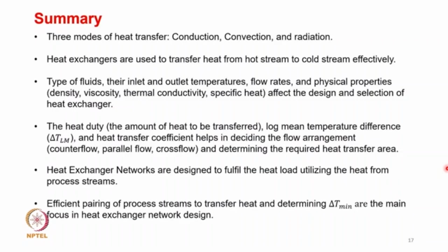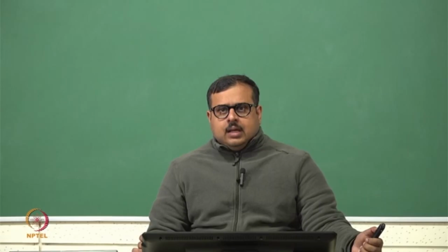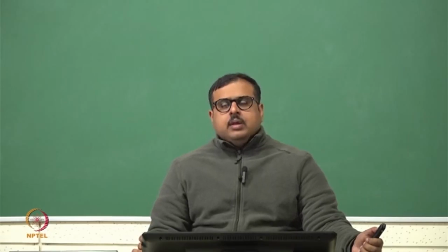Heat exchanger networks are designed to fulfill the heat load utilizing the heat from process streams, which are either cold or hot, by integrating them together. Efficient pairing of process streams to transfer heat, and determining delta T, are the main focus in heat exchanger network design. So, with this concept, we will move into the next lecture.